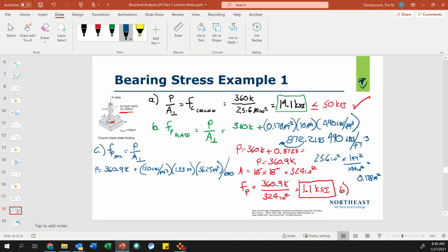Yes, that is right. So that footing, 16 inches high by 7'6" by 7'6", with the unit weight of reinforced concrete at 150 pounds, weighs 11,221 pounds. I'm going to divide that by 1,000, and I get 11.2 kips.